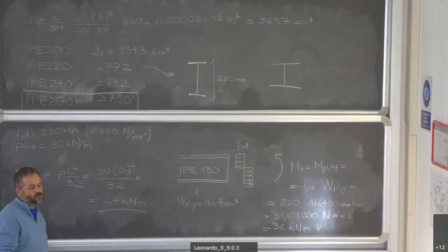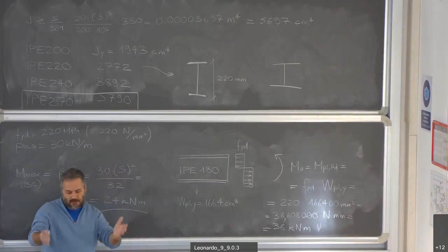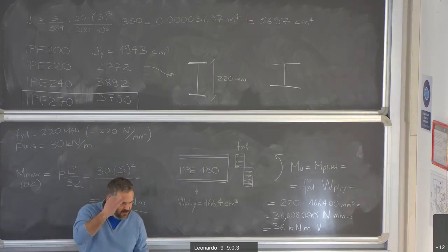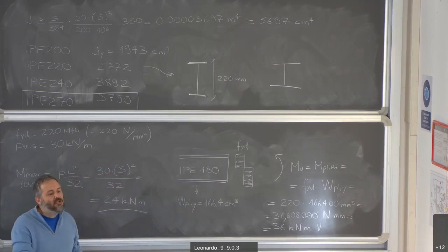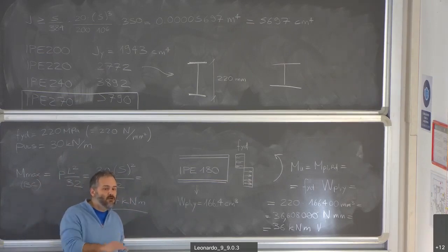Okay, so which means under service conditions, ordinary service conditions, your structure works. For example, this classroom, 300 kilograms per square meter. I'm inventing, okay? 3 kilonewtons per square meter, which means students crowd the room. When I do the ultimate limit states calculation, I'm looking at the structure to be safe for not failing.